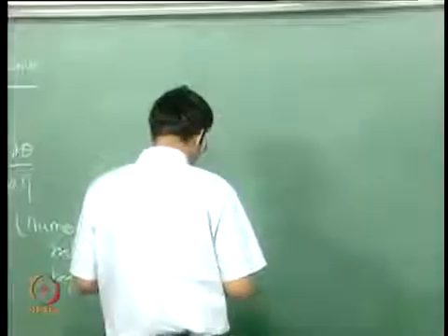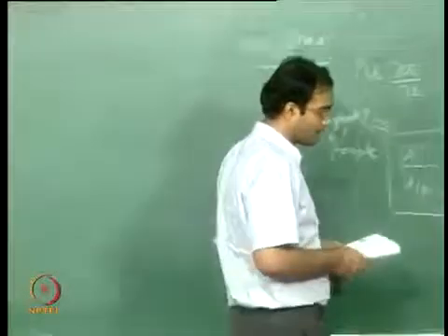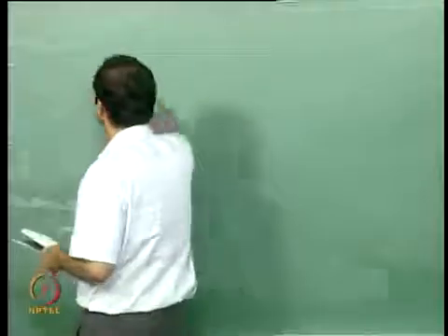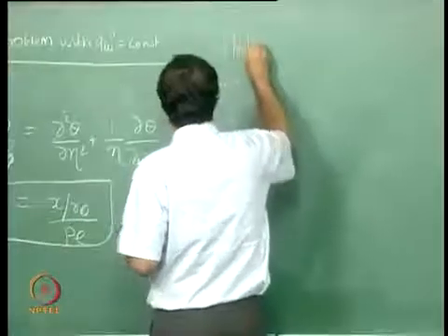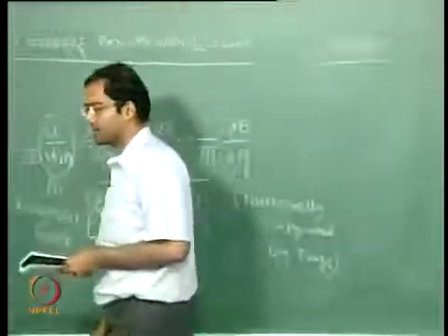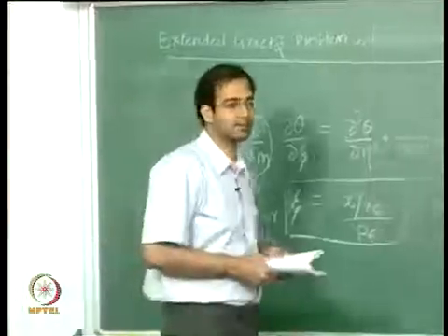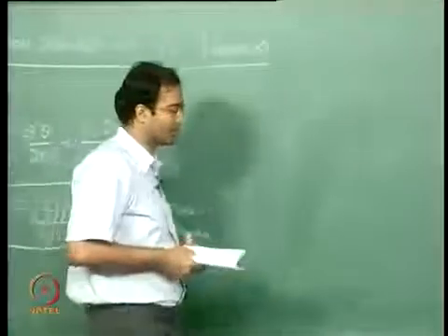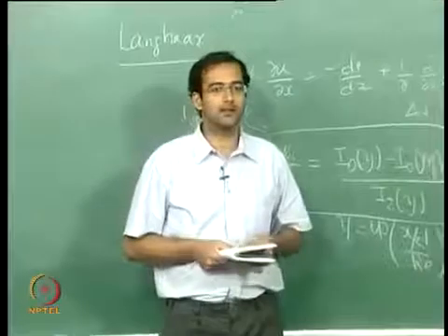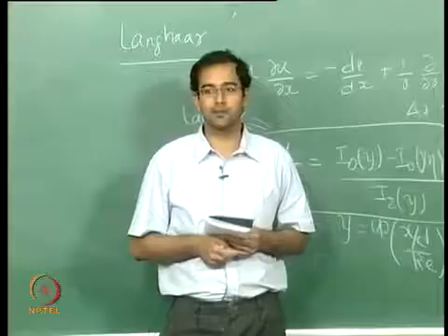And what happened was he found solutions, but then Hausen comes to our rescue, as we saw already that wherever there is a very complicated solution in terms of Bessel functions or Sturm-Liouville eigenfunctions, this fellow Hausen was kind enough to do an empirical curve fitting and give easier solutions in terms of only the Graetz number.